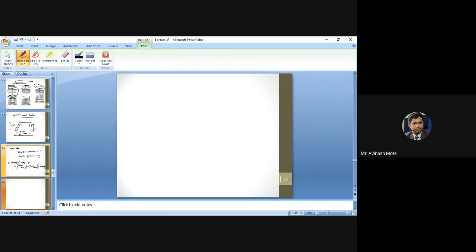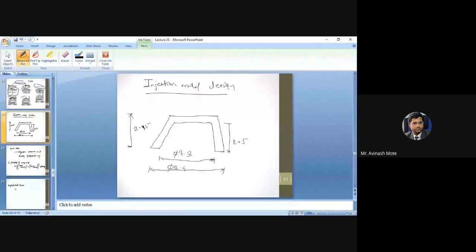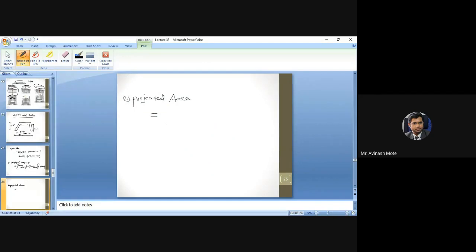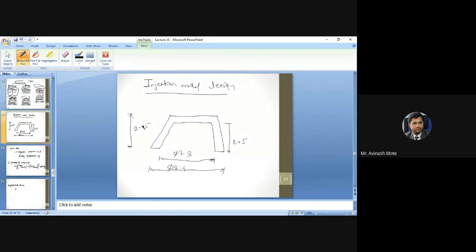Then the second thing you need to calculate as regular is the projected area. Simple, right? The projected area is the facing surface of the 3.4 diameter. If a rectangular section were there, the formula would obviously change, because the formula for calculation of area changes.